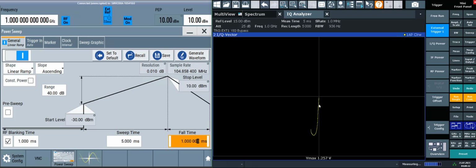So for every single point here, we could use the arctangent of the Q over I, and that would give us the phase at each point, and then perform a linear fit along some of the linear region points, and that would give us the phase deviation from the linear operation point of this amplifier. And that would be a good first order pass on amplitude and phase linearity for an amplifier.